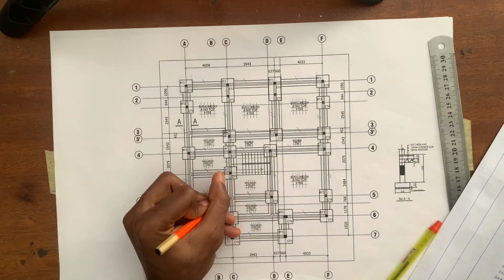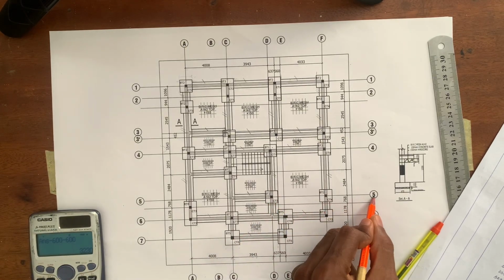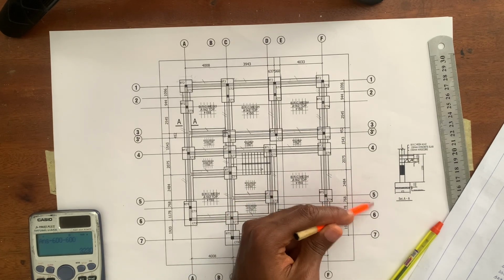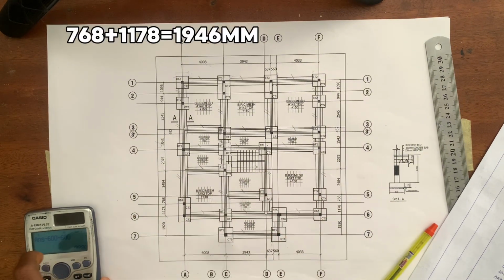So we're done for this part. The next part we're going to be doing is what? This part here, this vertical trench here. In order to get this vertical trench, you will trace this midpoint here to callout 5, and then you will trace from this midpoint here down to callout 6. In between callout 5 and 6, we need to get the distance. We are given two dimensions here, from here to here and from here to here. So we'll now add them together.